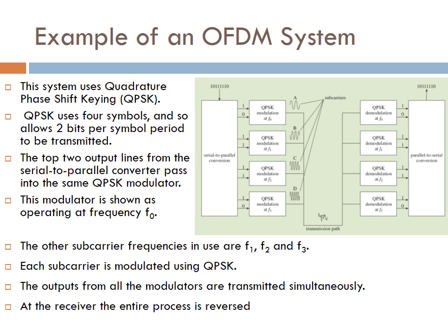The following figure shows one way of doing this. Start at the top left with the serial data stream 10111110, which is to be transmitted. This data stream passes to a serial to parallel converter, which converts it to 8 parallel streams of data. The top stream emerging from the serial to parallel converter carries the most significant bit, in this case 1.